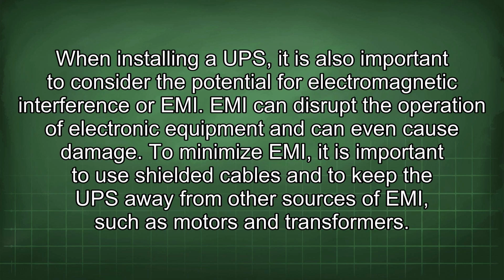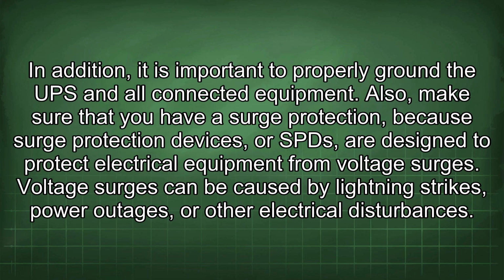When installing a UPS, it is also important to consider the potential for electromagnetic interference, or EMI. EMI can disrupt the operation of electronic equipment and can even cause damage. To minimize EMI, it is important to use shielded cables and to keep the UPS away from other sources of EMI, such as motors and transformers. In addition, it is important to properly ground the UPS and all connected equipment.